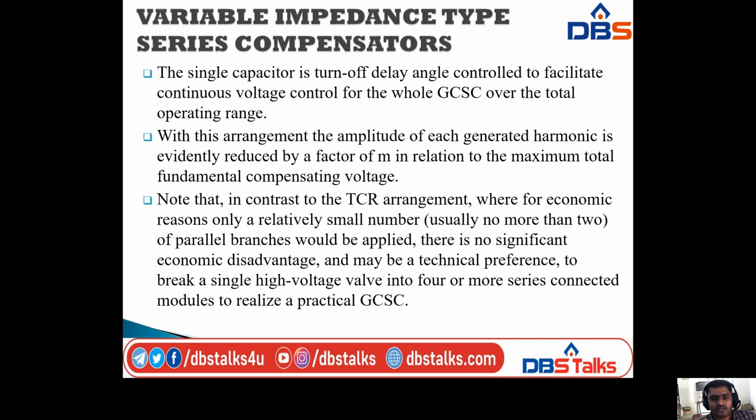Note that in contrast to the TCR arrangement, where for economic reasons only a relatively small number of parallel branches would be applied, there is no significant economic disadvantage, and maybe a technical preference, to break a single high voltage valve into four or more series connected modules to realize a practical GCSC. So this is the explanation from the previous slide, with the four GCSC schemes.